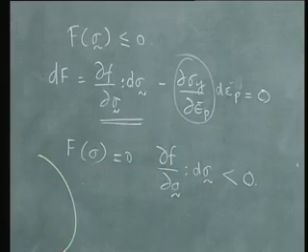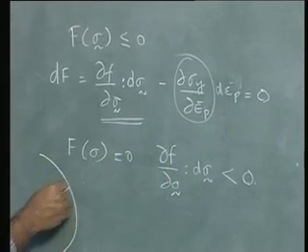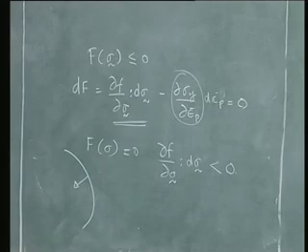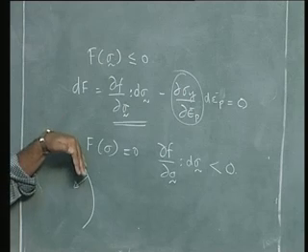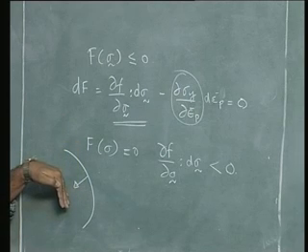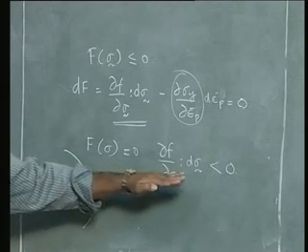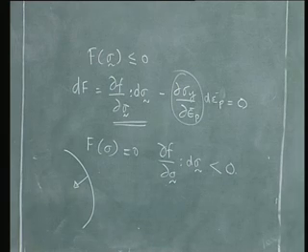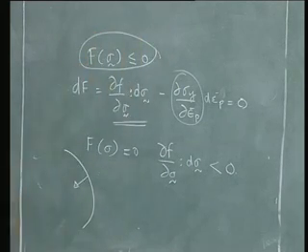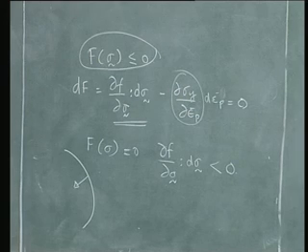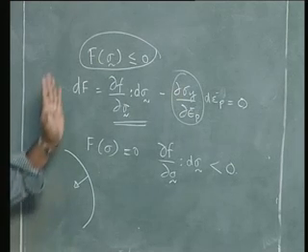So if this is the yield surface, when I have unloaded it, I would have come in, leaving the yield surface. So this way I am reducing the first part of the story. So now this would have come in. That is why dou f by dou sigma d sigma is less than 0. In other words, f can be less than or equal to 0. Now when I unload, what would happen to f?